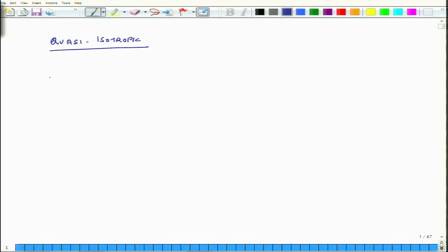Now, if we look at an isotropic material, let us say steel, and then we try to develop its A matrix, then for isotropic materials the A matrix looks something like this: E t over 1 minus nu square, nu E t divided by 1 minus Poisson's ratio square, third element 0, this is also 0, this is 0, this is 0, this is a symmetric matrix.